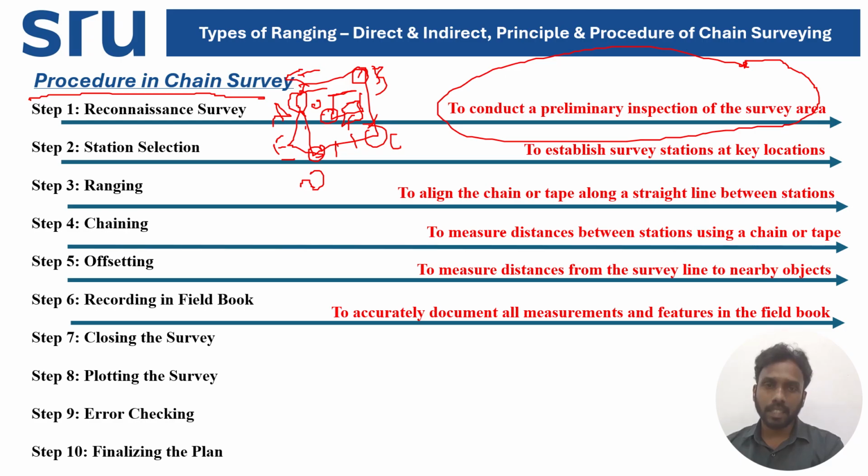If any particular data is missed, it may cause a cumulative error. If it is a cumulative error, you have to start your surveying again from the first and do the entire work again. To avoid these things, you should be very precise and cautious while doing your measurement and converting your data from the measurement to your drawing, to a document.